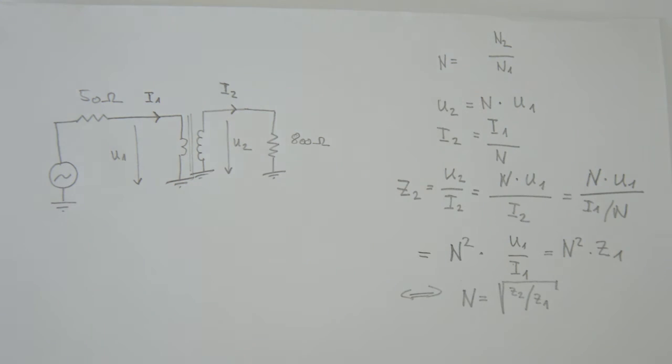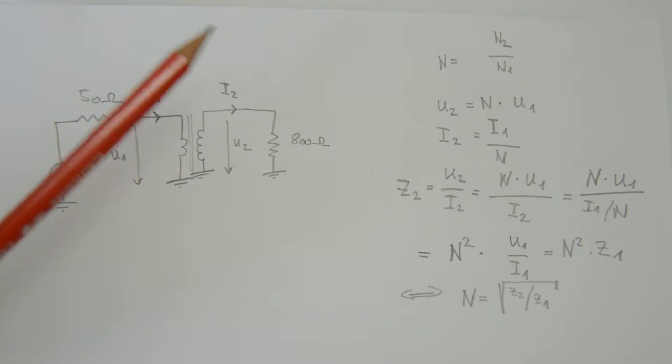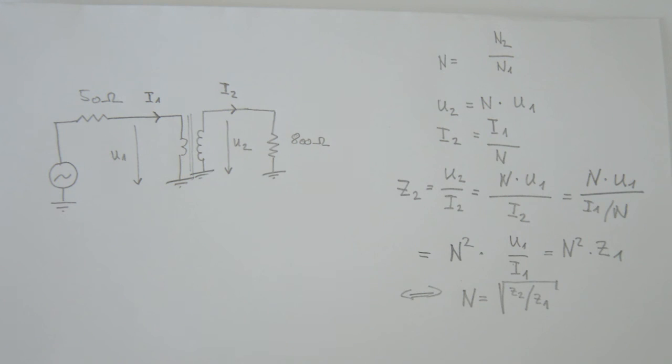The idea is that if you put an L match there, that match is only going to work out at 10.7 megahertz, and otherwise you'd end up with a mismatch again. So putting that transformer here allows you to get a pretty broad frequency range at which impedances are matched. And I will actually run an experiment where I demonstrate how this can be useful.